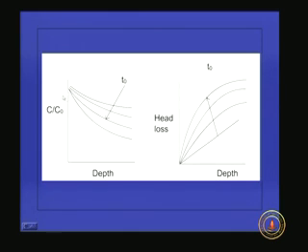But with respect to time, what will happen? The turbidity removal efficiency is getting reduced and reduced. Here we can see the reduction is not much. So, these are different curves at different times. This is initially, that means the filter has just started operating, and as time progresses, the filter operation efficiency is coming down.